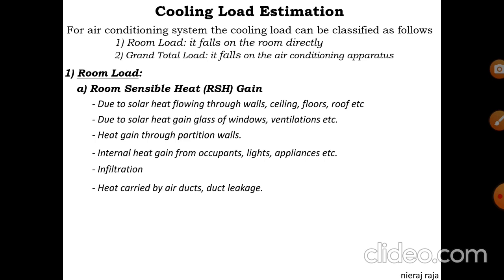Through the ducts also there is heat transfer inside that room, because inside the duct there is cool air, but outside the duct, which is open to the atmosphere and the building passages, they will carry certain heat, and when they enter your air distribution unit inside the room, they may carry some more heat with it. And if the duct leaks, more outside air will enter that duct, and it can finally enter your room. So ultimately the room sensible heat would be changed.